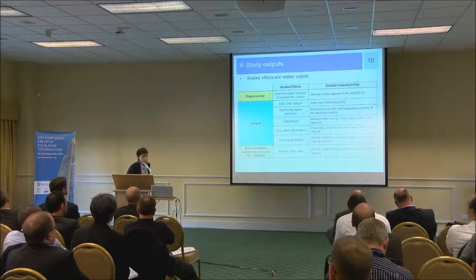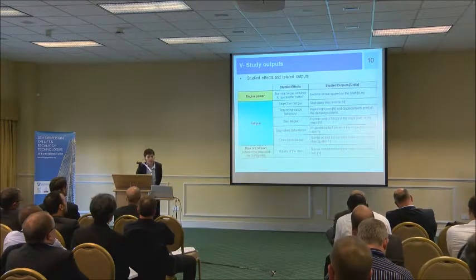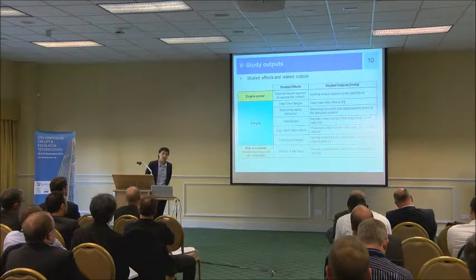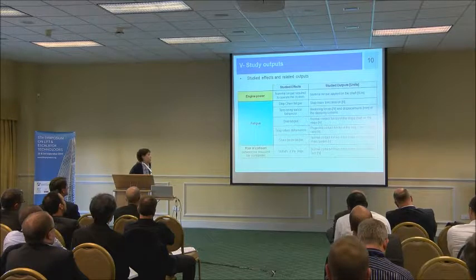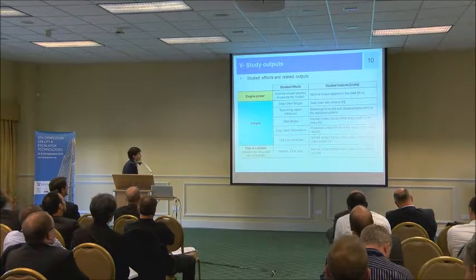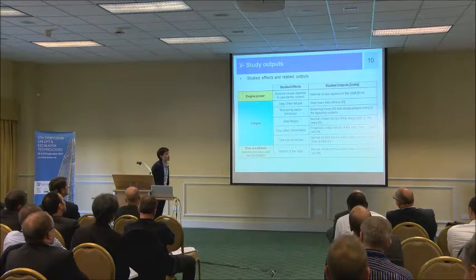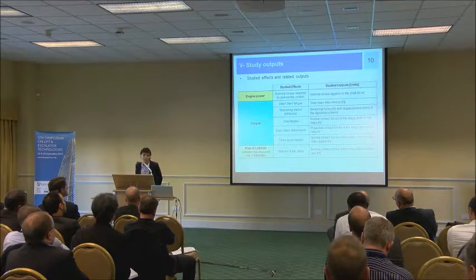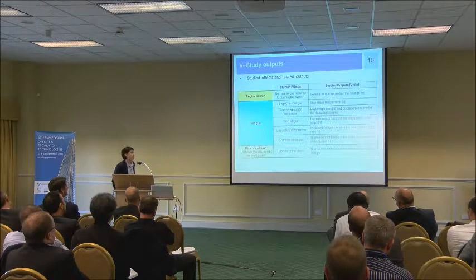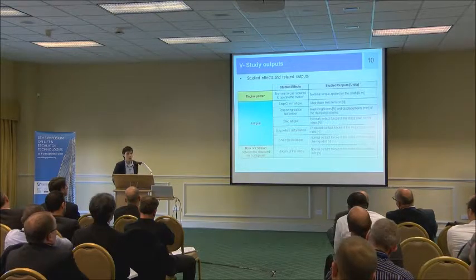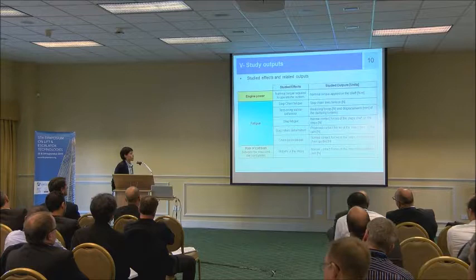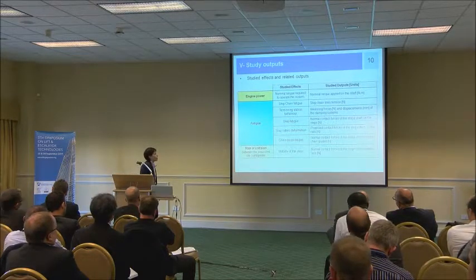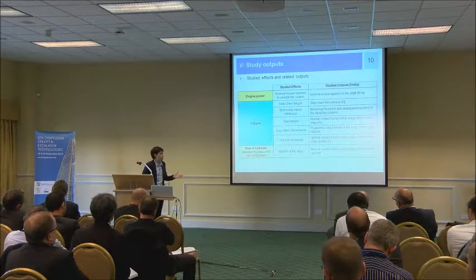So for instance, to study the chain guide fatigue, we recorded the contact forces of the step chain on just the chain guides. As you can imagine, a model like this has some limits. The biggest one is that to reduce the computation time, we had to guide the steps using the tracks. So the steps, of course, can roll. They can have lateral displacements, but they cannot rise.